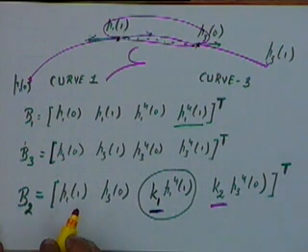Okay, there are models in which continuity is ensured, C1 continuity. But even there in FEM there are certain models in which continuity is not ensured. Then you don't bother about it, that's all. But then why do you use those models if you cannot ensure continuity? What is the use of those models? Because FEM does use 12 degree of freedom elements. In that, C1 continuity is not ensured.